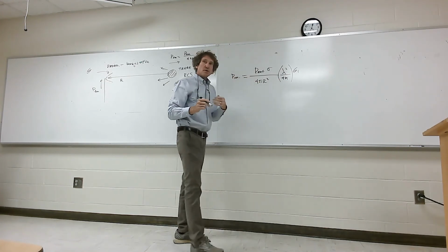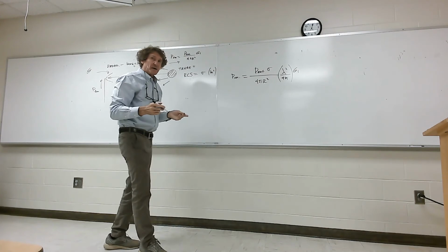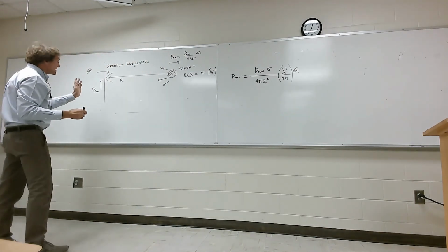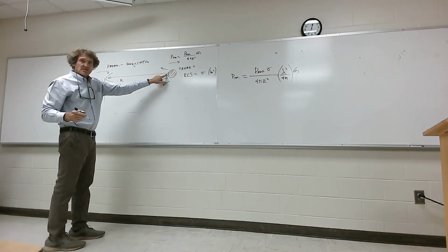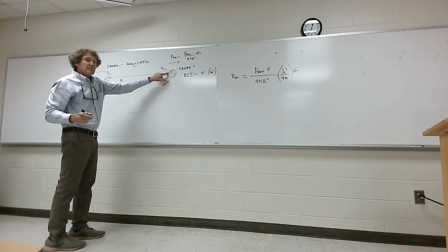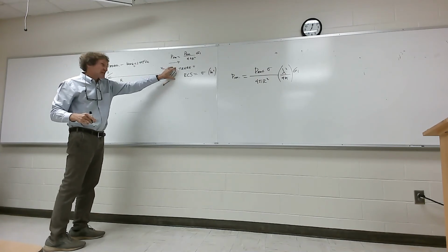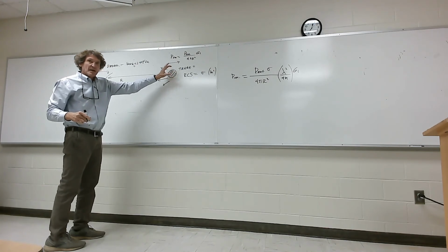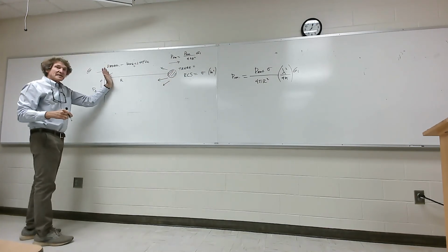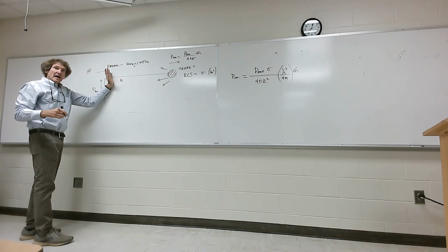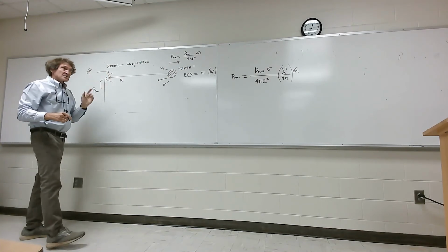I'm going to go ahead and put in all the terms of this. What you're expected to know with a radar problem is how much power density is on the target, how much power is radiated back or scattered by this object, the target, then the power density back at this antenna, and then the amount of power received by that antenna.